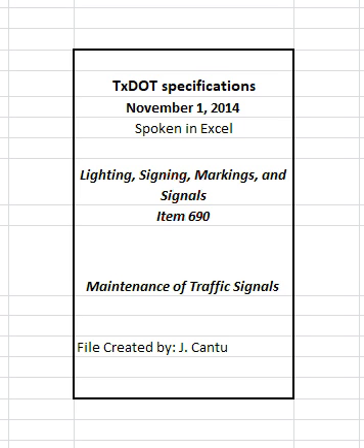Remove timber poles and anchors completely, to 24 inches below ground level, or as directed. Remove concrete foundations to 24 inches below ground level, or as directed. Install, repair, replace, remove, or modify pedestrian signal pole assemblies in accordance with Item 687, pedestrian pole assemblies, as shown on the plans, or as directed. Install, repair, replace, remove, or modify roadside flashing beacons in accordance with Item 685, roadside flashing beacon assemblies, as shown on the plans, or as directed.